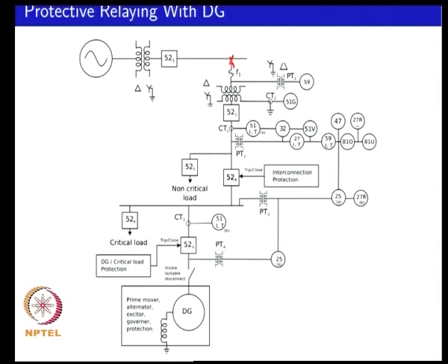So, you may not be able to have the voltage exactly at the nominal value. There might be some acceptable range like plus 5%, minus 10%, and you want to keep it within that range. You want to do that not just for one particular location, you want to do it all along the feeder.